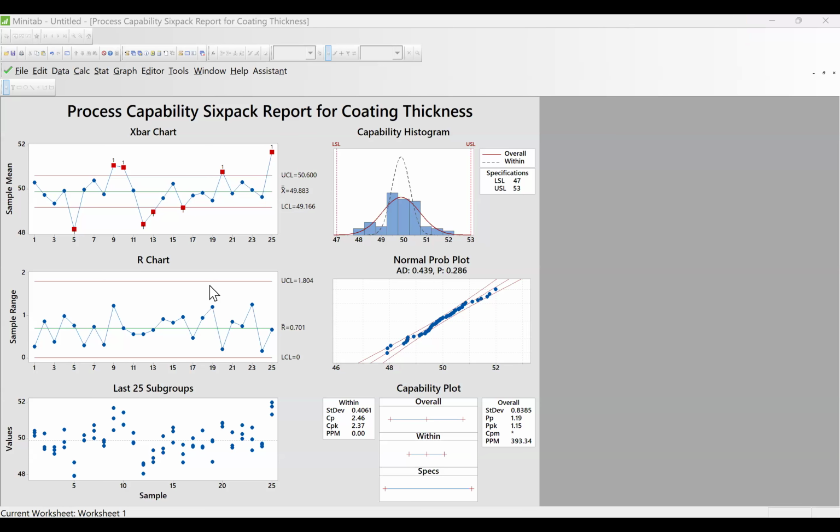Clear? Sir, one question. On what basis is Minitab showing that on the long-term process, the PP/PPK value will be lower? Is it based on the X bar chart? No. There is a calculation available that I want to explain later, because if everything comes at the same time, you might find it difficult to understand. So I will come back and then clarify the CPK. But right now, yes, PP/PPK is unacceptable, but CP/CPK is acceptable. That means for this process, as far as the short-term application is concerned, there is no issue. Noted, sir. Good.